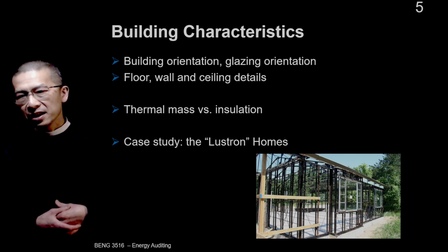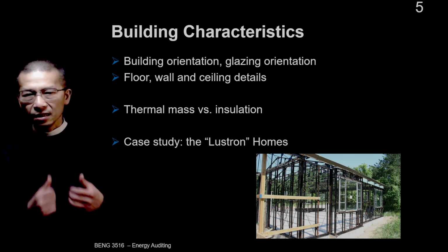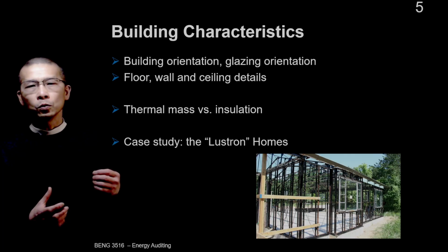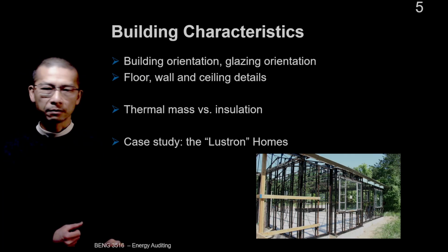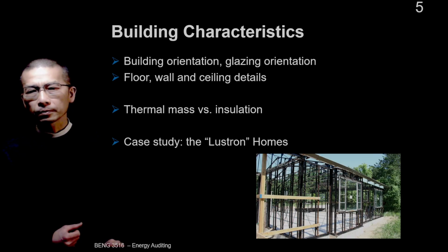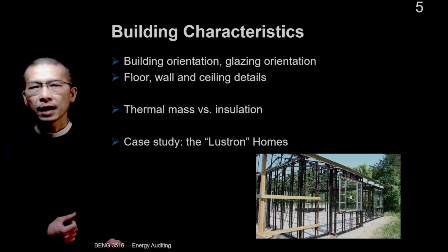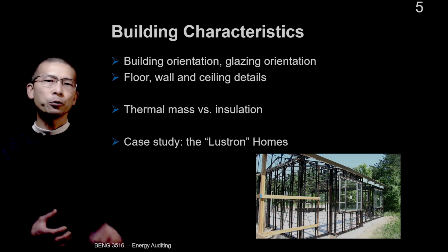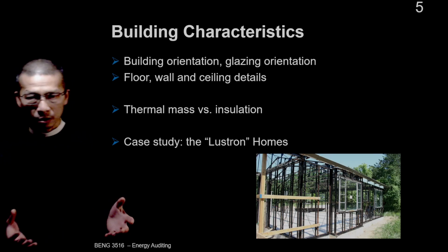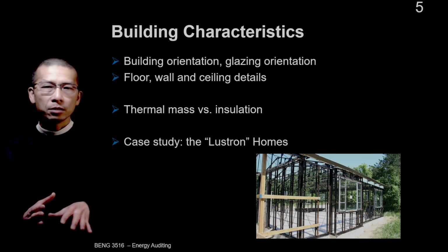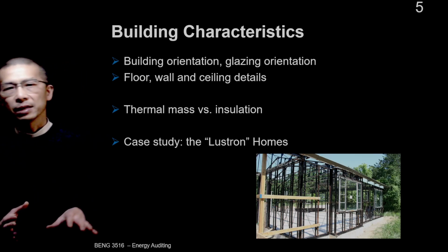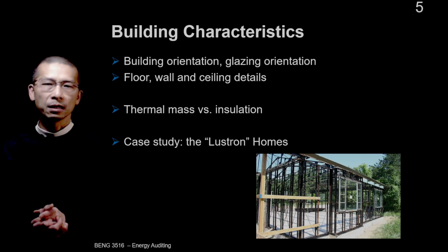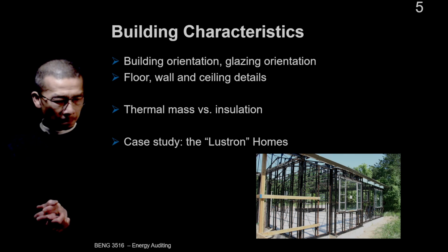So the key objective here is to define thermal boundaries, okay, the thermal boundaries. If you cannot tell exactly where the insulation starts and stops in these details, you cannot accurately estimate the building's heat loss.